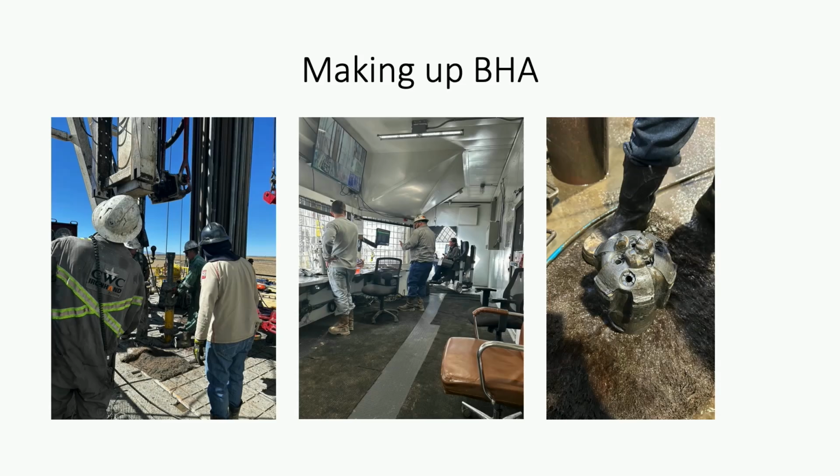And on the far right is one of the bits that just got absolutely destroyed. If you're not following the right practices to conserve your bit, they'll just mash on it. Some of those rigs will put 50,000 pounds of weight on that bit, and if you are not babying it, you will destroy it. Sometimes we'll twist off, as they call it, downhole, and we'll lose our tools completely because it's just so much power that something has to give, and we lose all this stuff downhole.